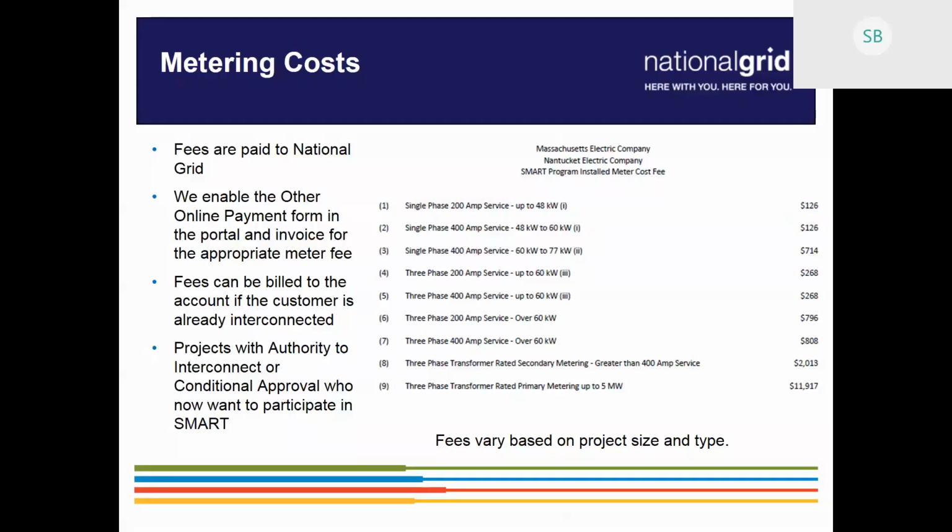Well, again, the first one about the AHJ, or the wire inspection authority, has been the standard rule for decades too, right? Until the world of SMART came along, people don't understand normal service upgrade requirements. It was always a requirement for the inspector to look at these things and approve them, and if you wanted a separate service, there always was that local requirement to approve that. And that's also part of the National Electric Code. It's got nothing to do with SMART. So that's the other challenge we have: the electricians who've been working in the field know the code and understand that, but some of the new folks in the field aren't clear about it and think it's new, and it's just going back to the basics of upgrades.